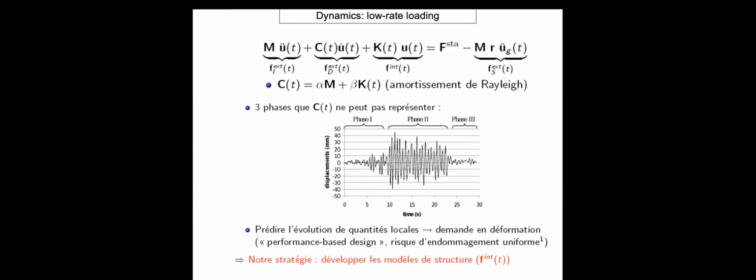Obviously, if you do Rayleigh damping, you cannot capture all this because you can only fix 2 frequencies and get the corresponding damping coefficient. It is not worth repeating what you had in linear analysis, because you are not going to do it here, that's for sure.